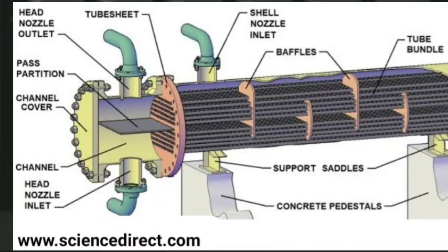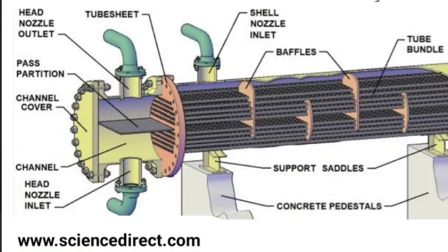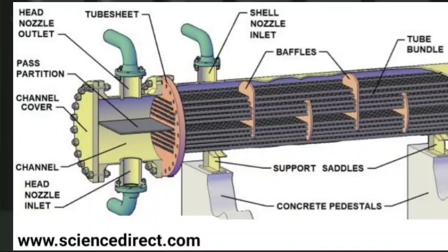If the channel length is 500 mm and the nozzle is not within the diameter limit, then we have to increase the channel length. If it is not fitting in your limit, then you have to increase the channel length. But if you increase the channel length, then the fluid flow also you have to check with your process, whether it will be okay or not.